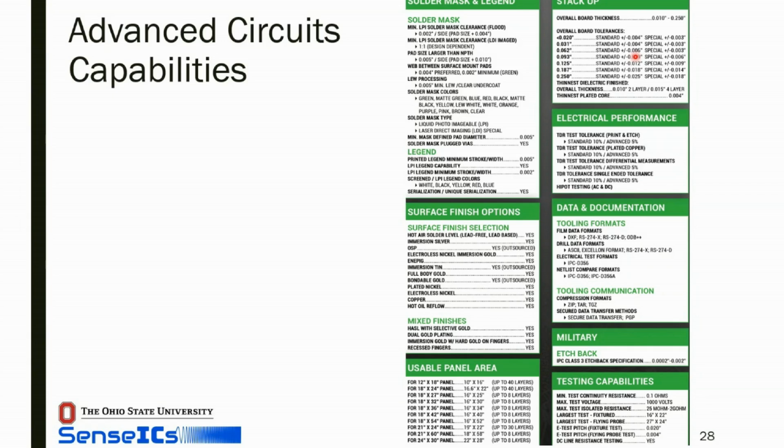So we didn't really talk about it, but that dielectric thickness is typically 62 mils, okay? That's the most common thickness. So we talked about green is the most common solder mask. Well, 62 mils is the most common dielectric thickness. Would anybody like to answer or propose a reason to get a thicker dielectric or a thinner dielectric?